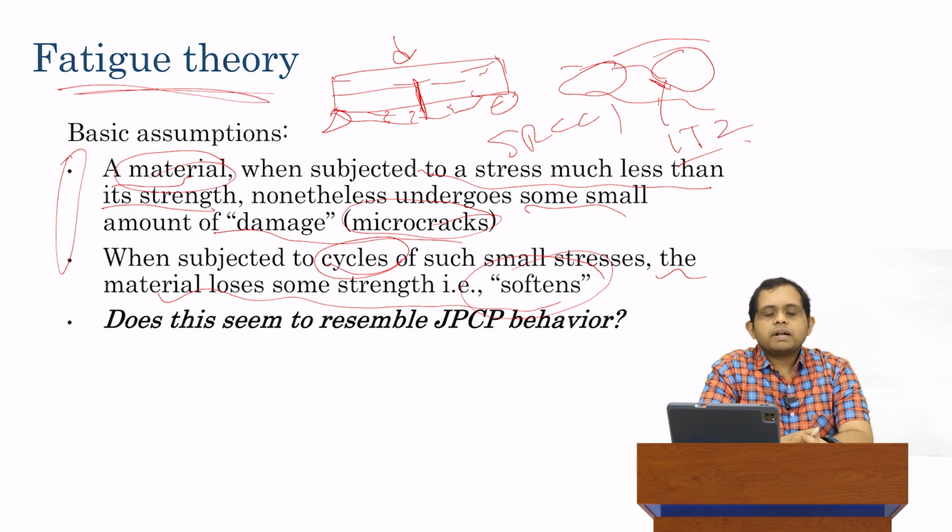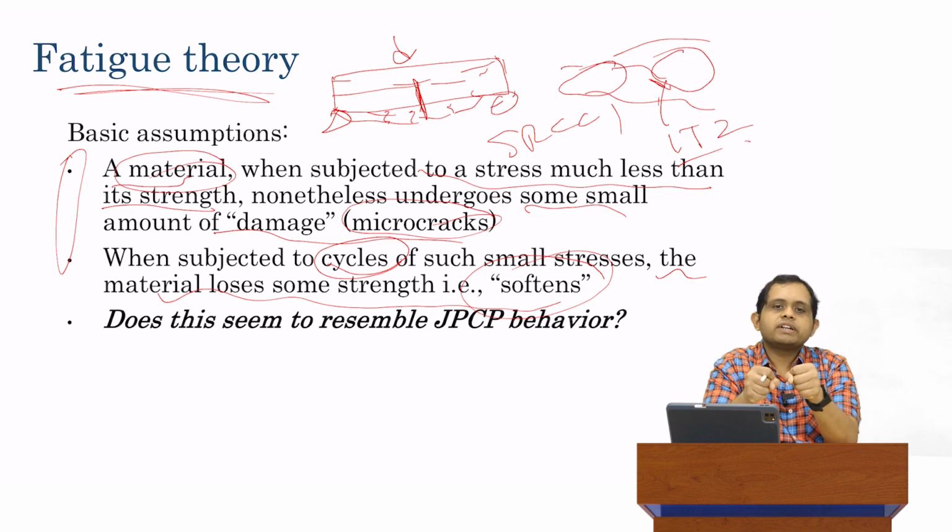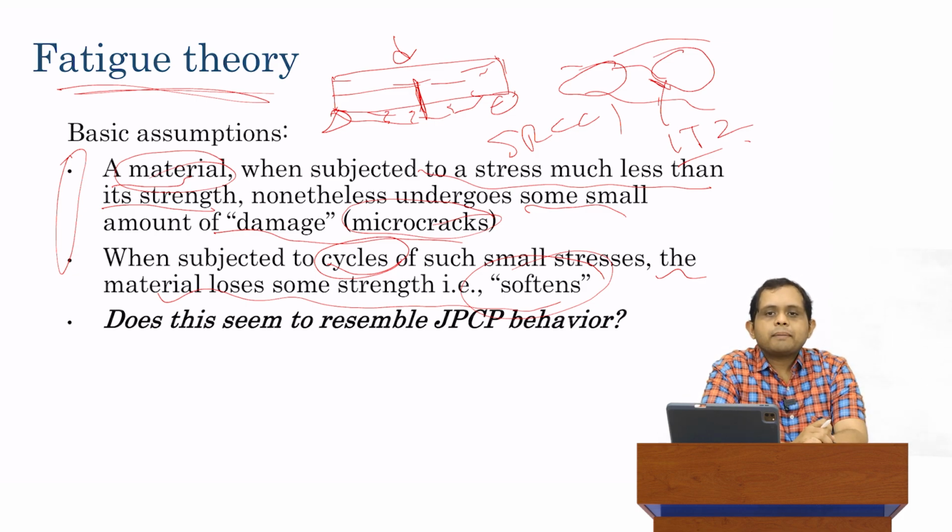But instead, if you start applying small loads, if you just move it a little bit and bend it a little bit, you'll see that after several such applications, you are able to break the rod into two. You are not able to break the rod by applying one strong load, because you need a very high amount of load for that, but you are able to do it by applying very small loads over several cycles. That's a very common and typical example to show fatigue.